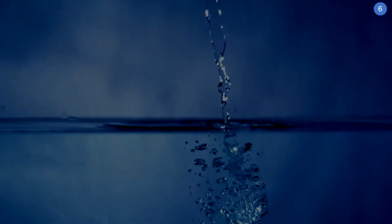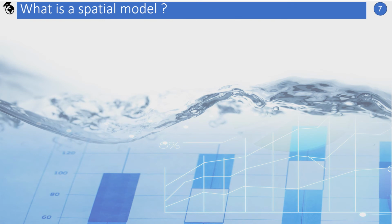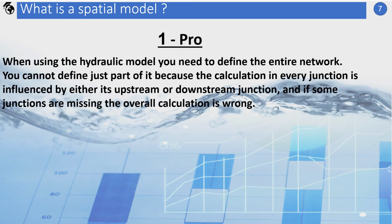What are the differences between the traditional methodology which is based on hydraulic model and this new methodology which is based on a spatial model? There are some pros and cons when you compare these two methodologies. 1. When using the hydraulic model you need to define the entire network. You cannot define just part of it, because the calculation in every junction is influenced by either its upstream or downstream junction, and if some junctions are missing, the overall calculation is wrong. With a spatial model on the other hand, you can start even with a small portion of the network, and expand your calculation gradually.